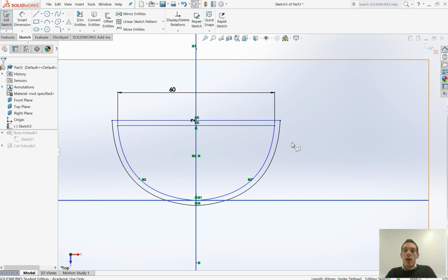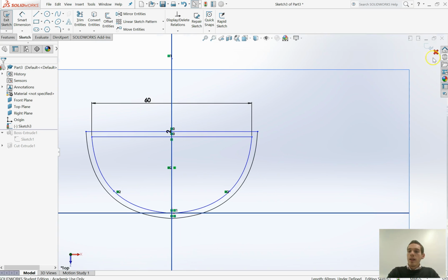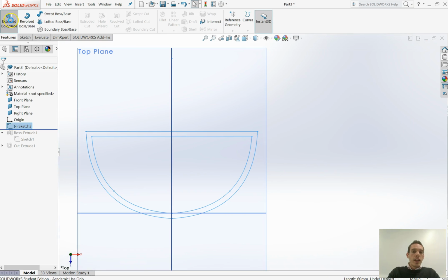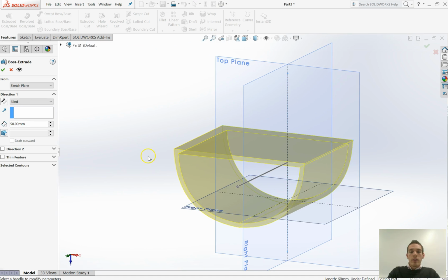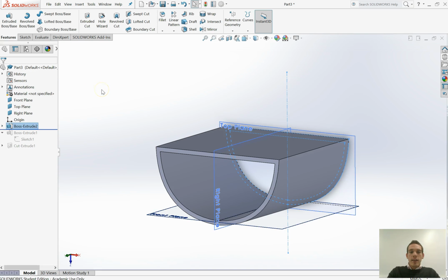If you have a hole or something like this, where you've got an outside border and an inside border, when we go to extrude, we'll only end up extruding this middle bit here. So I'll just show you that. If I exit the sketch, I'm happy with that now, I'm going to go Features, Extrude, click on that sketch, use the middle scroll button to move around, and you will see that I am now just extruding that element there. I hope that makes sense, okay? Set your extrusion, etc., and click OK.